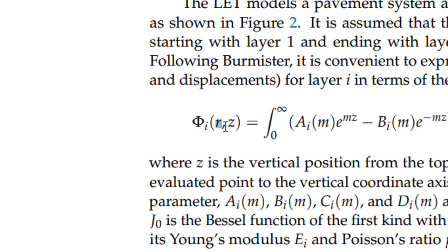Another important thing is the analysis step. If you are studying the LET theory, a static general step for linear elastic analysis is okay. Since it's linear, the solution is straightforward, with no need for multiple increments. But if there are multiple loads or moving loads, maybe different steps are involved.